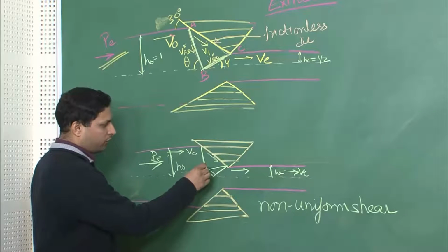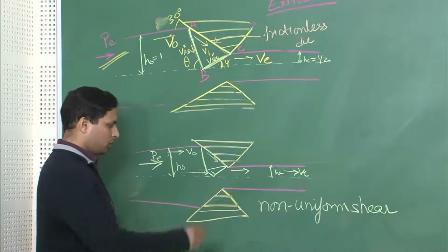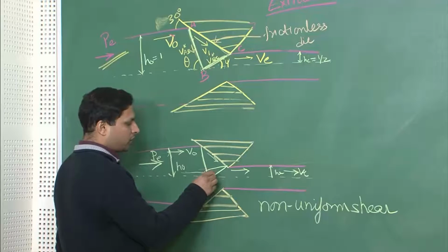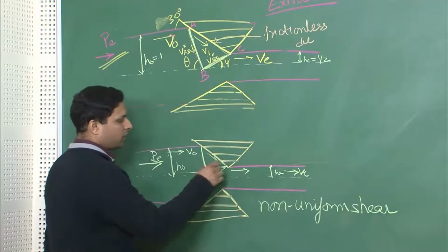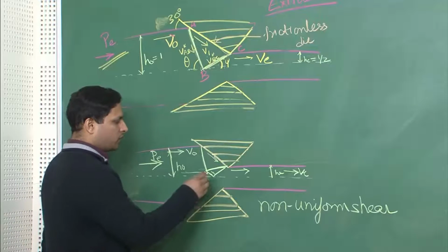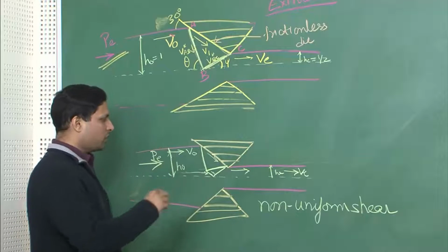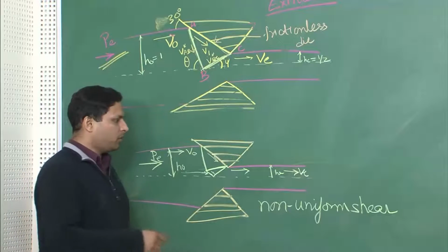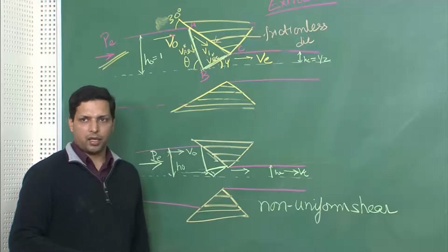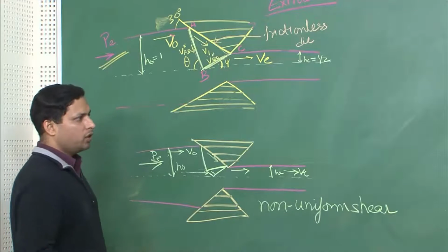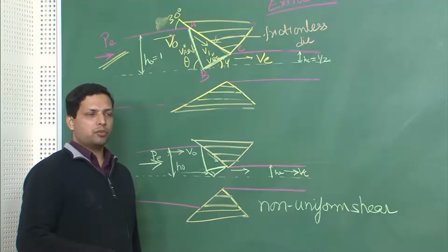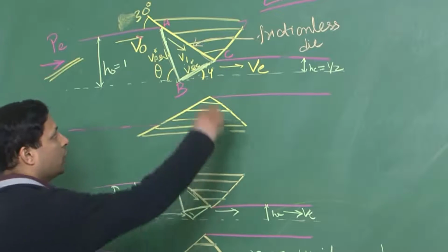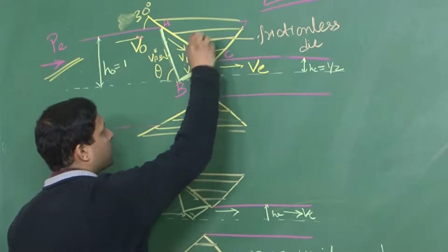And now, since you have defined two different slip planes or two different shear zones, you will have to have different shear velocities over here, and there will also be another shear velocity over here. So, those parameters will have to be put into that equation, and because of the hodograph and the geometry, since you know the geometry, you will be able to define all of those and hence get the magnitude and direction for all of them, and eventually you will be able to get PE in terms of K. Another aspect that we need to consider here is that we said that this part is frictionless.